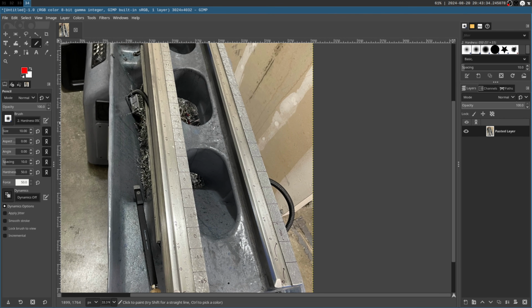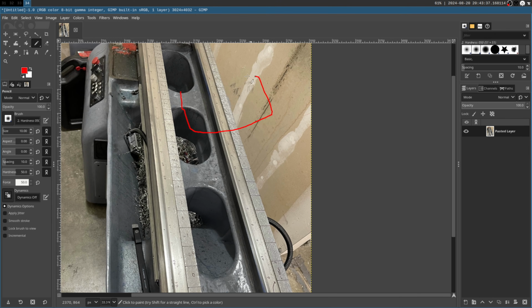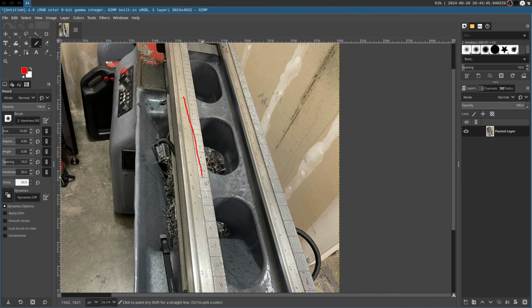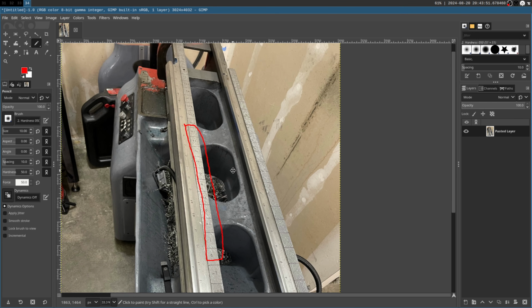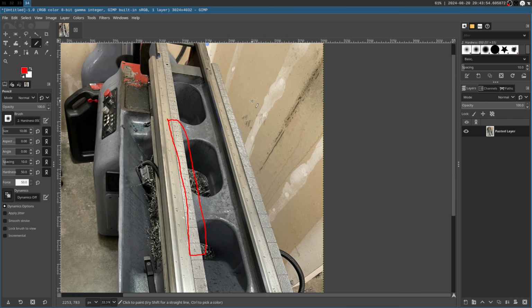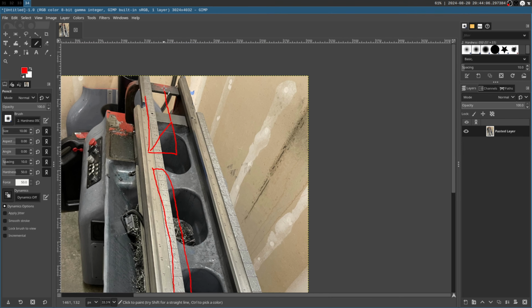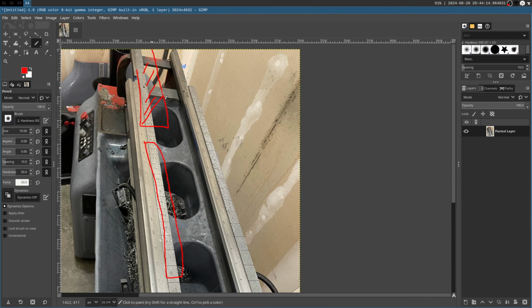And also, I've noticed from some of my other scraping projects where I've scraped things that are square or round or rectangular but relatively wide, with these very narrow and long ways, it's very hard to get a feel for your contact. You could have a situation where the way is angled up like a sawtooth, right? You have this triangle, and you're measuring the flatness of this surface here, but you don't realize that you're twisting this edge the whole time.